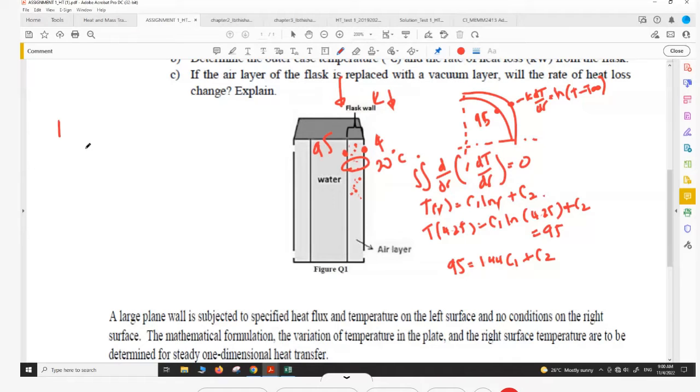Okay, for the second boundary condition, you need to solve this one. So dT/dr is basically, if you solve this, you're going to get dT/dr equal to C1 divided by r. But since we are working at r2, so dT/dr at r2 equal to C1 over r2. So you replace this inside here, you're going to get k C1/r2 equal to h (T minus T ambient).